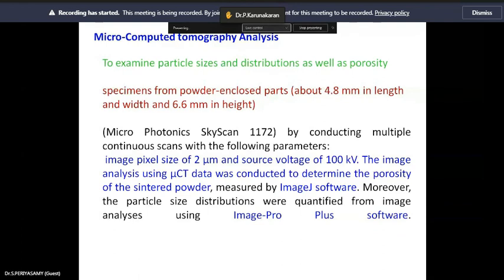So the residual stresses, here we can easily find them from a normal method. Here the residual stresses originate in the solid layers and the substrate underneath the newly applied layer. This imposes tensile stress on the newly deposited layer. So with one layer and another layer, the cooling and shrinking, that is the cooling rate, is varying.